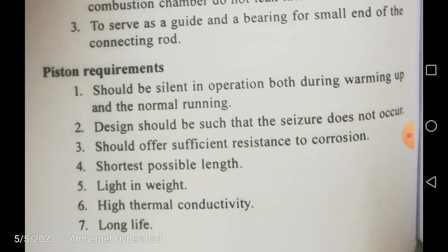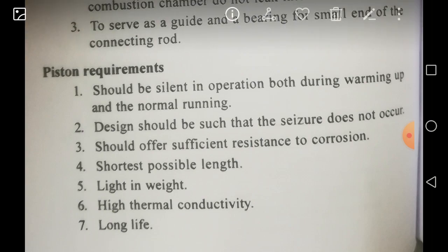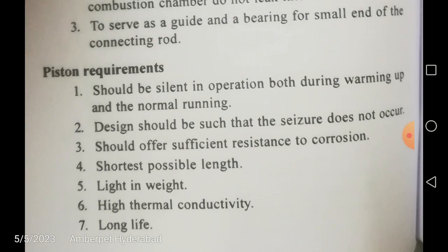And now what are the piston requirements? It should be silent in operation so that there is no sound, and a rough operation should be avoided; it should be silent both during warming up and normal running. Number 2, the design should be such that seizure does not occur. Sometimes the piston is seized between the cylinder walls and the piston, so it will not move. So it's called seizure. Third one, it should offer sufficient resistance to corrosion. The piston should not get corroded very easily, otherwise it will be rendered useless.